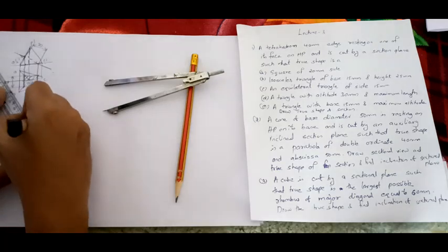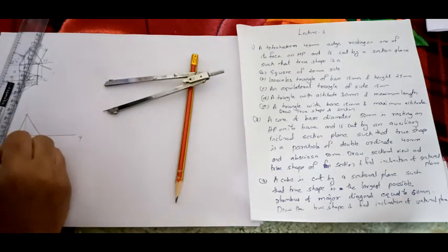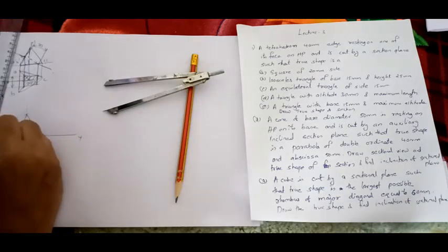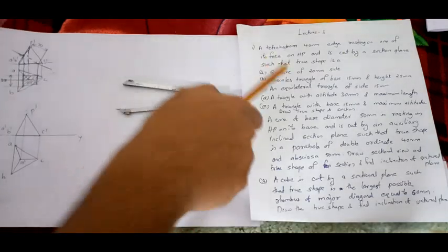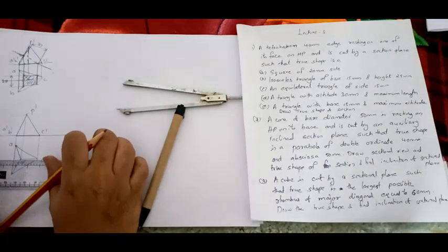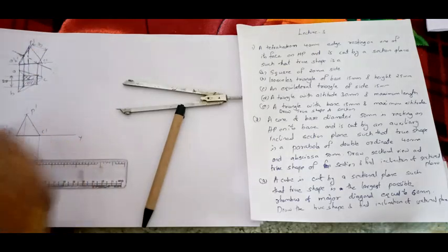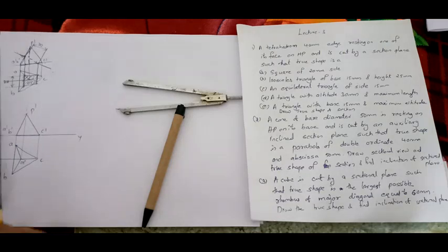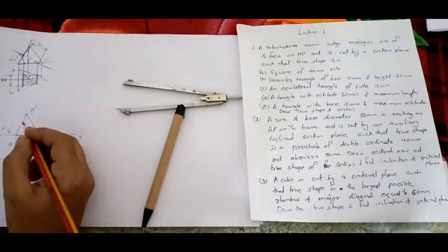And for the tetrahedron you will not be having any height. So complete it. This will be your B dash, A dash. This will be C dash and P dash. Now I'm going to start the problem. So you have to obtain a square of 20 mm side. For that, as I told you last time, this is symmetric, right? So I will extend this line. Now I will take 10 mm upwards and downwards.